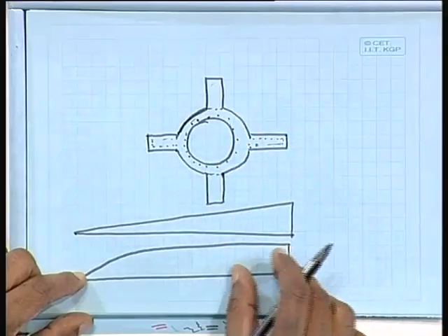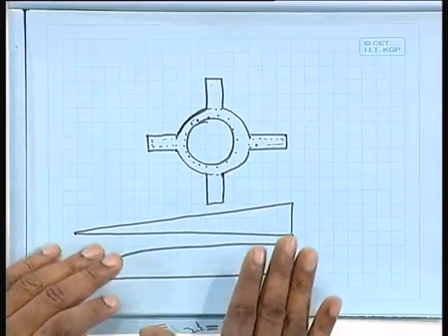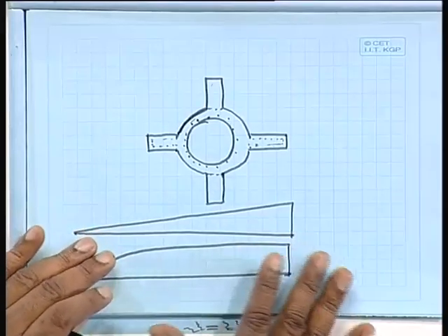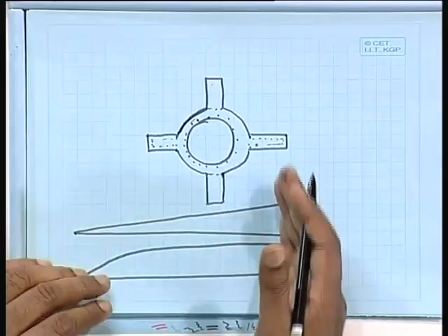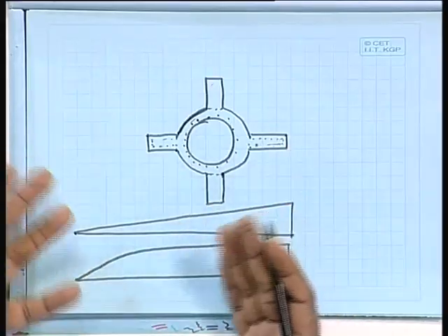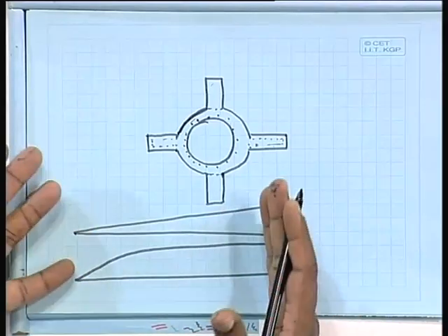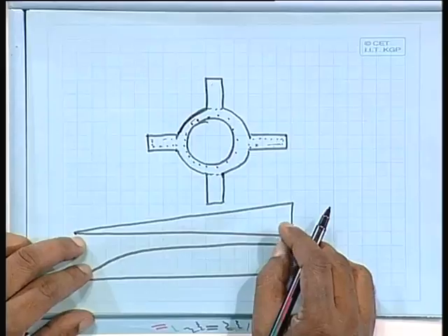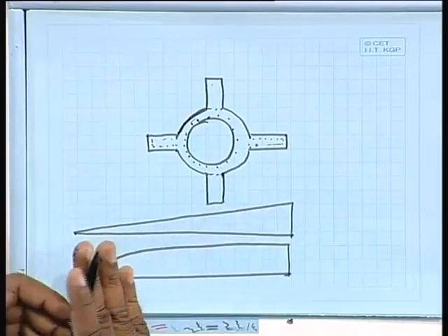If you can understand the stress diagram and strain diagram of the limit state method of concrete design, immediately you can find the moment capacity and axial load capacity. That is what we are doing here, and it is very simple: 0.0035 and 0.002 are the different strains, and on the basis of that you can find out.